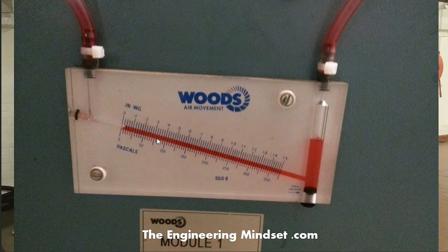And this will change as the pressure increases across there. There's no pressure drop at the moment, but as this goes down, as the filter becomes more and more dirty, it becomes greater and greater. So this is measuring the difference between the intake and the suction side across the filter, and that's how you know how dirty it is.